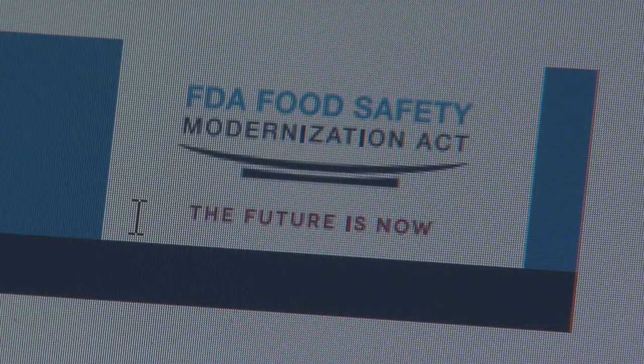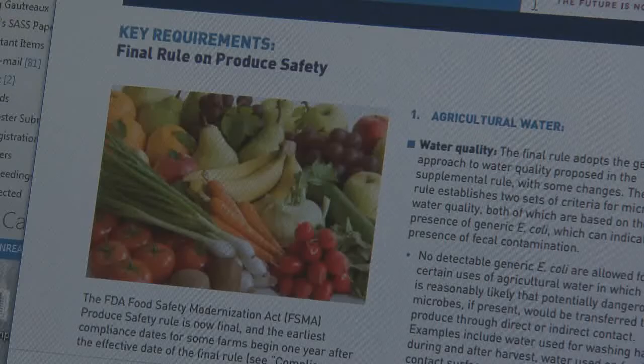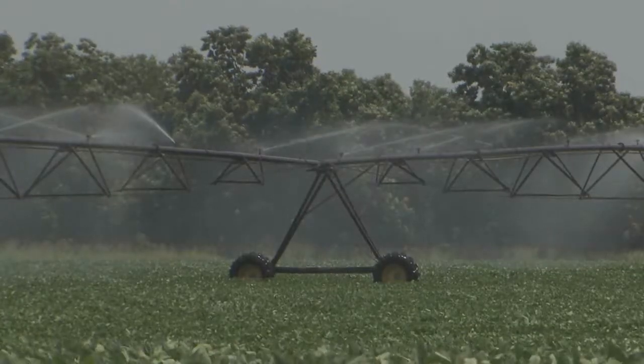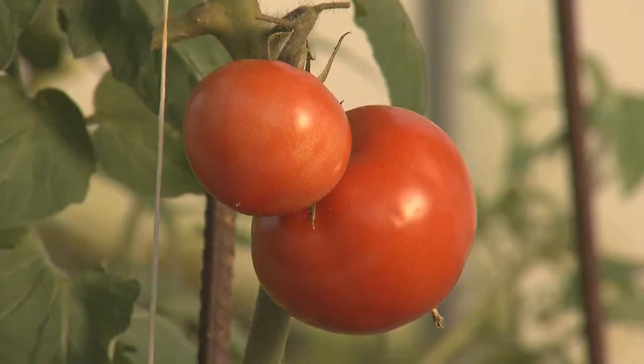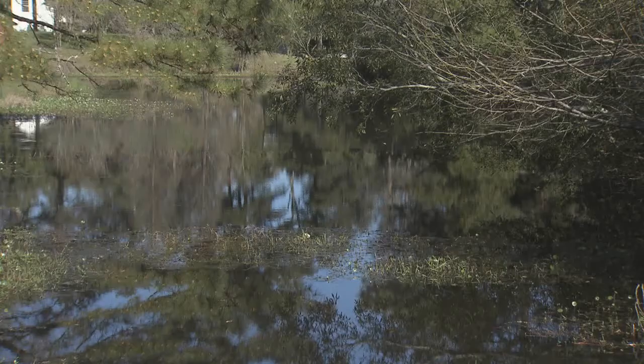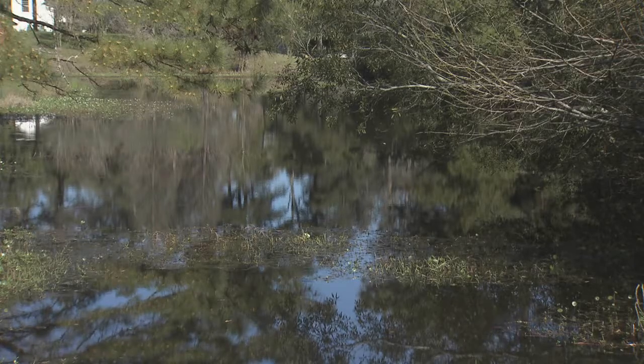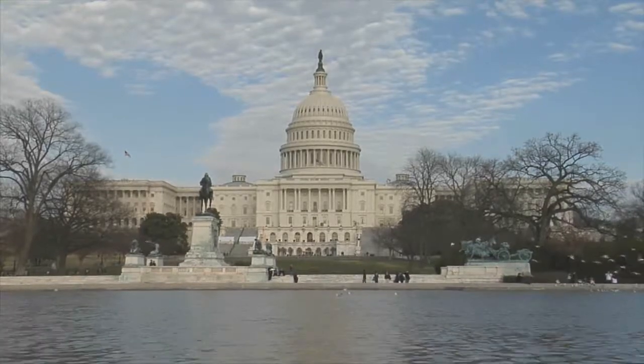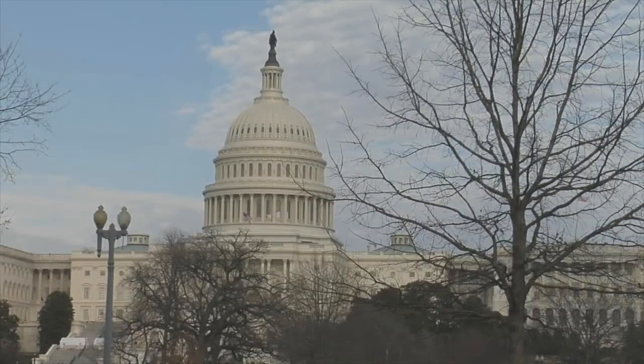The Food Safety Modernization Act Produce Safety Rule requires all agricultural water to be of safe and sanitary quality for its intended use. Water used for pre-harvest practices and that will be in direct contact with the edible portion of the raw agricultural commodity should meet the generic E. coli requirements as proposed in the U.S. Environmental Protection Agency's 2012 Recreational Water Quality Criteria Standard.